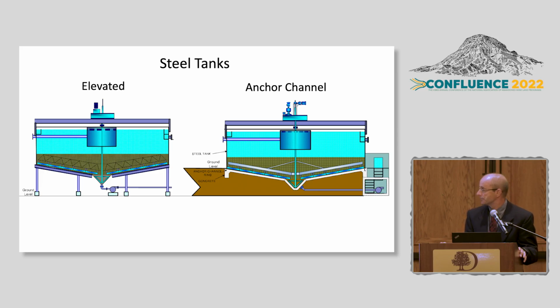The disadvantage with this design is it's difficult to put the underflow pump directly next to the discharge, because you have to excavate a tunnel, so that means confined space issues and other safety issues. So you usually need to put the pump outside the perimeter, and now you have a longer suction pipe line. It's still okay, it's used effectively often, but you may need consideration like flushing the line or a duplicate suction line in case there's problems. So that unit is very inexpensive, commonly used on large diameters.